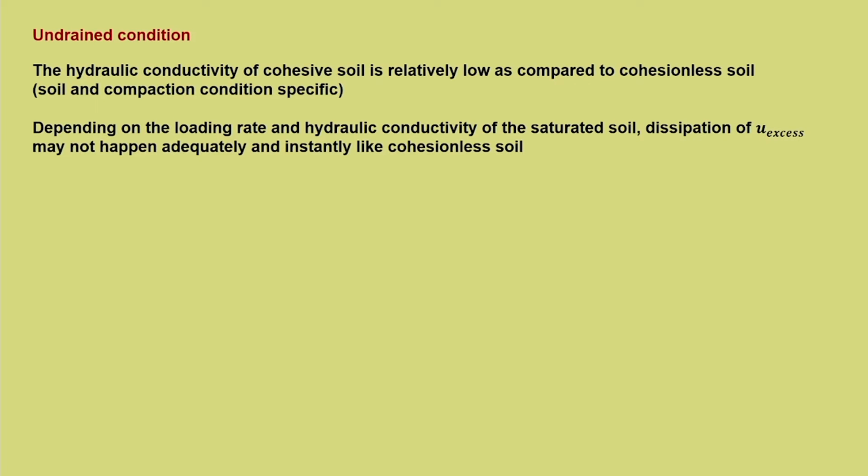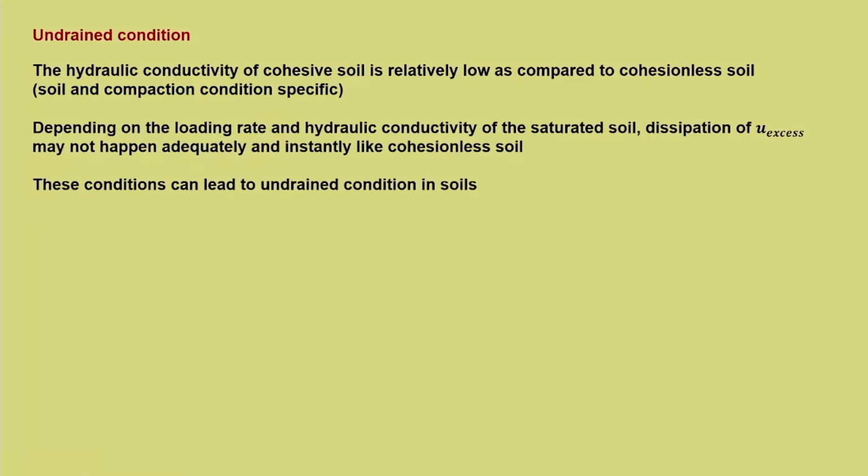Only when the water is allowed to move out to expend the energy, then it will come back to its original state, and when it tries to achieve its new equilibrium state, there will be some changes that will happen to soil, and that is how we say the total stress is transferred to the soil as intergranular stress or effective stress.